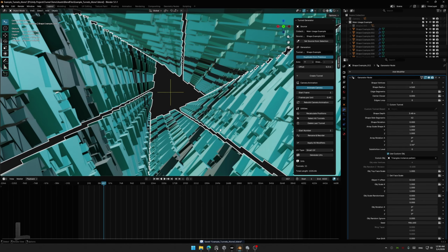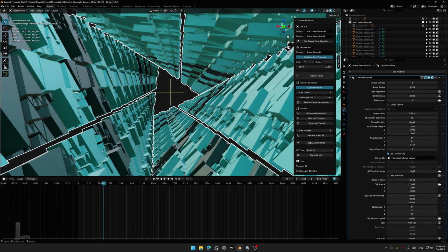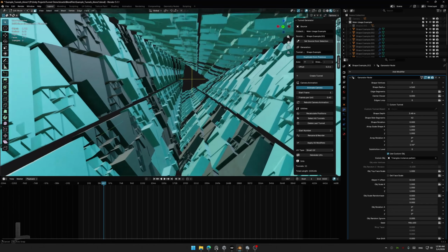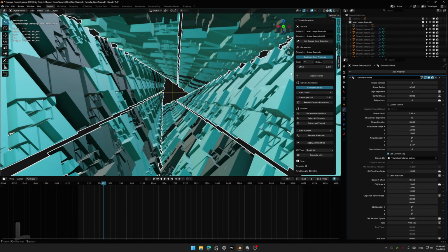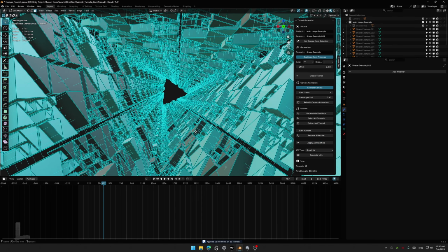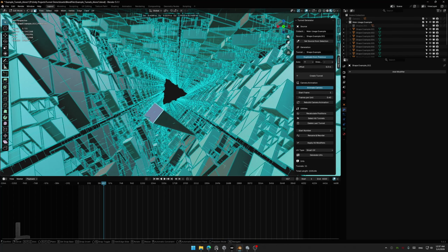Two last things you need to do before exporting or doing anything. Probably you need to make UV maps, so you need to apply the modifiers. And the modifiers in this case is the geometry node procedural system we have. If I, for example, enter the edit mode, there is no geometry. So I need to apply all modifiers. And if I enter edit mode, I now can edit any shape I want.